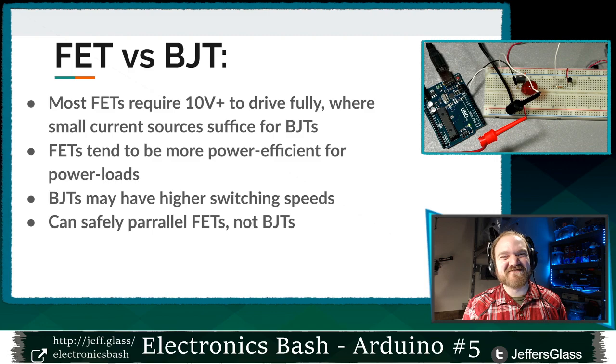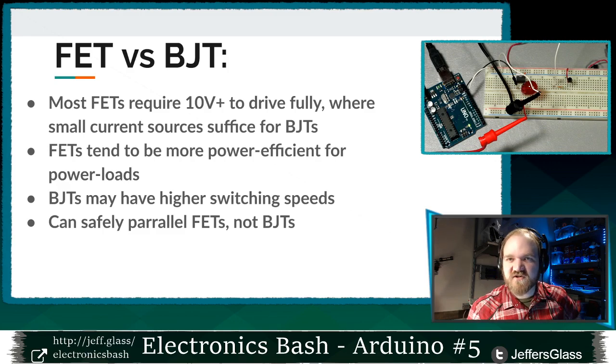Much less heat losses in a FET than in a transistor for most of those higher current applications. Transistors tend to have higher switching speeds, tend being a really loosey-goosey word. For our purposes, it doesn't really matter because, again, doing something hundreds or thousands of times a second is not really high speed for these devices.